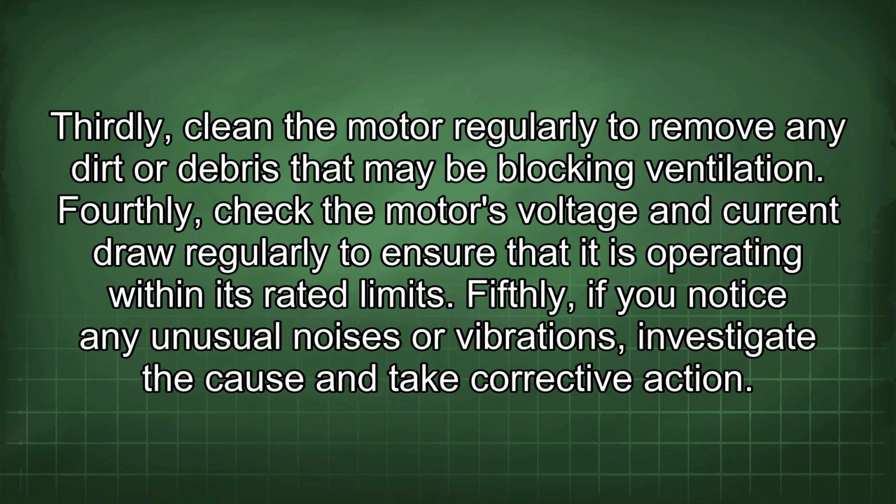Thirdly, clean the motor regularly to remove any dirt or debris that may be blocking ventilation. Fourthly, check the motor's voltage and current draw regularly to ensure that it is operating within its rated limits. Fifthly, if you notice any unusual noises or vibrations, investigate the cause and take corrective action.